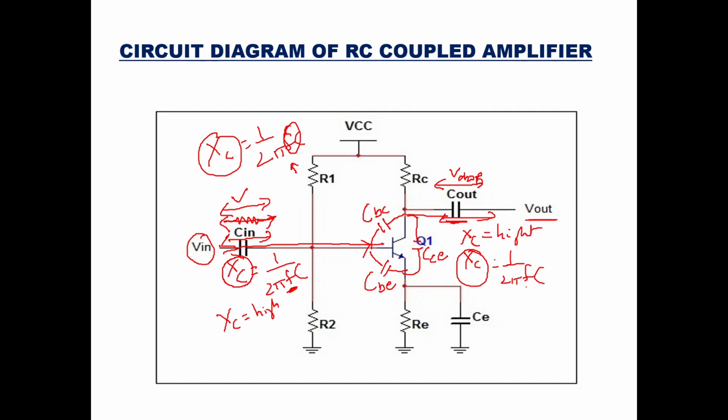Now this capacitance is acting as a feedback from output. This is output and this is input. So from output to input, you are giving a feedback. The current which was generated at the output in a larger magnitude is going back to the input. And this is how your output voltage gain will be reduced. Output voltage developed will be reduced because of this inter-electrode capacitance.